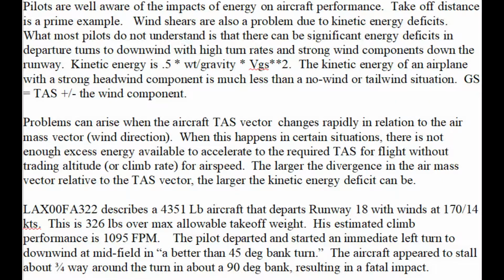Pilots are well aware of the impacts of energy on aircraft performance. Takeoff distance is a prime example. Wind shears are also a problem due to kinetic energy deficits. What most pilots do not understand is that there can be significant energy deficits in departure turns to downwind with high turn rates and strong wind components down the runway.